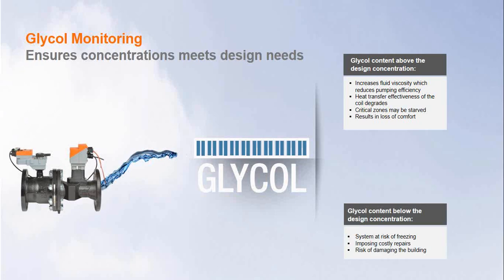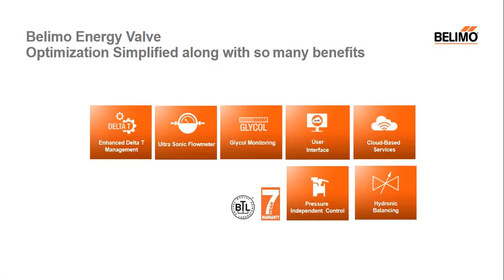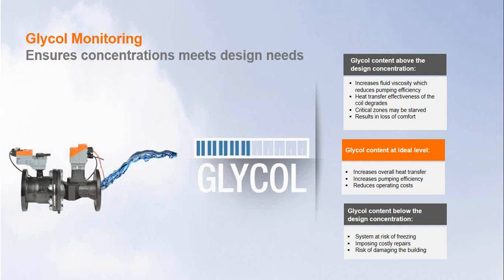Once again, on the heat transfer side, there could be situations where excessive glycol in the system will impede the ability to meet discharge air. Coils are designed for specific glycol concentrations, and if it's too high, you could have a situation where you do not meet the discharge air because the heat transfer performance is so degraded by excessive glycol concentration. So overall, you would have a result in comfort as well in the space. So setting it at the ideal level increases our overall heat transfer, increases our pumping efficiency, and reduces our overall operating cost.